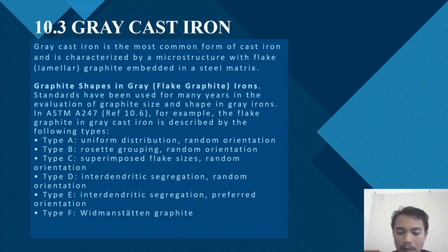On the other hand, the following properties decrease with increasing tensile strength. So the low strength irons often perform better than higher strength irons when these properties are important: machinability, resistance to thermal shock, damping capacity, and ability to be cast in thin sections.